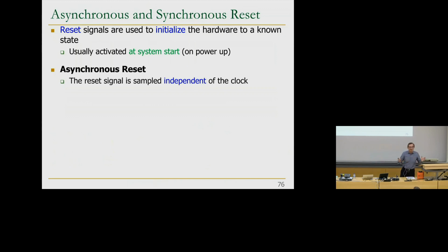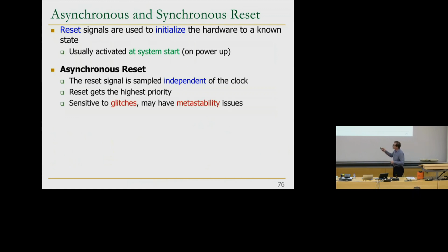Asynchronous means you don't have a clock, or you don't respect the clock. Basically, in this case, the reset signal doesn't respect the clock, or the flip-flop doesn't respect the clock, in the sense that the reset signal is sampled independently of the clock. It gets the highest priority. This has issues, because if you do stuff without respecting the clock, you may have issues like glitches and metastability, which we will talk about tomorrow. But there are cases where you use asynchronous reset also.